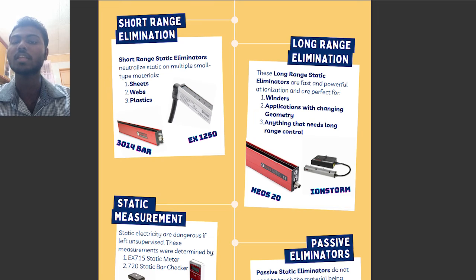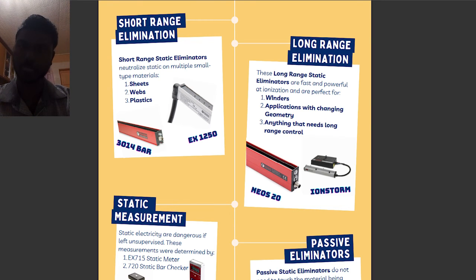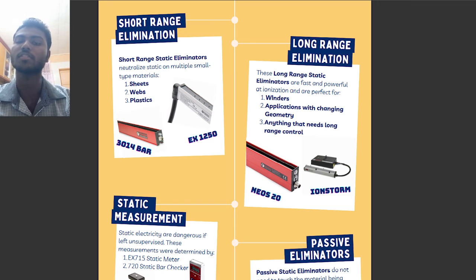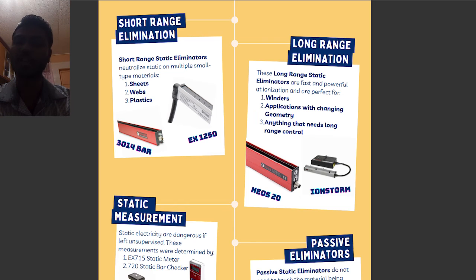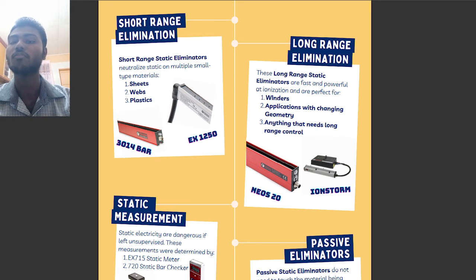The last one is heat and static. For example, a plastic product is not electrically stable until it is cooled to 40 to 50 degrees Celsius. It is a typical target figure for electrical stability. The significance of this is that a hot molding can generate some charge after neutralization if it is hot. This argues that static neutralization should wait until the molding has cooled down to 40 degrees before neutralization.